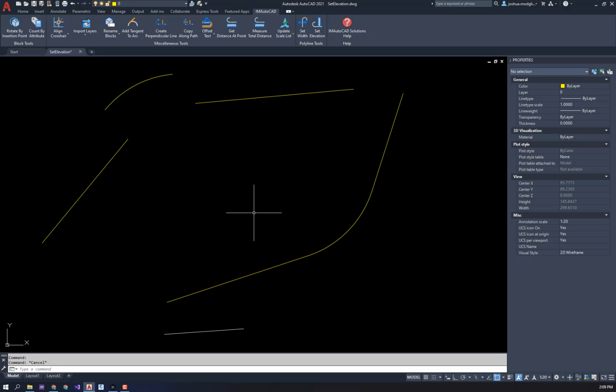So it's a great way to, especially if you're working in 3D, even if it's, let's say, civil and you're doing some manual contours, and it's a great way to work and set those elevations. So that's really where that tool came from. Some were using polylines for contours and we're needing to set elevations along the way. Some point to match with cleaning up a drawing where there might be polylines used for contours or lines and arcs. The Set Elevation tool came into existence for that, but can be used for so many other benefits, especially when working in 3D.